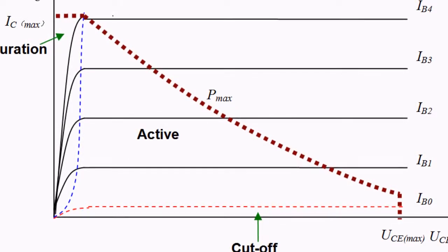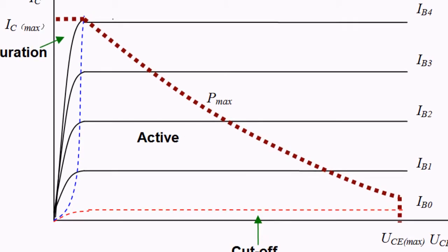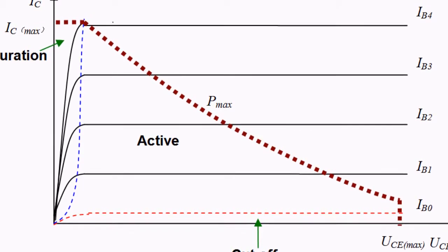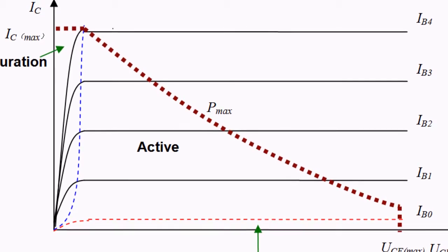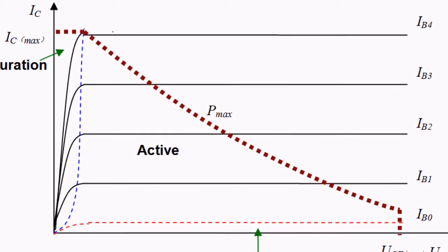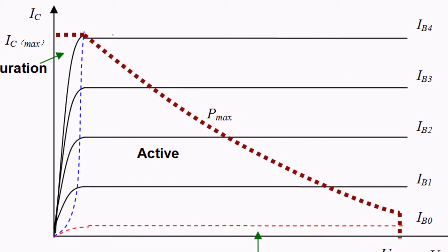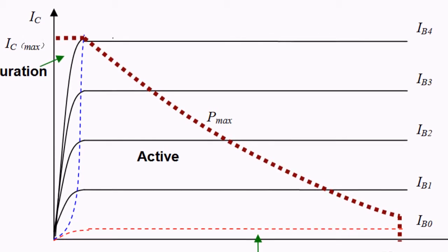We studied this in our Electronics 1 when we were third year, during the first semester, and we have learned that in a transistor, there are three basic regions of operation. These are the cutoff, active, and saturation regions. The active region is the operating range of the amplifier. The transistor operates in the active region between saturation and cutoff.